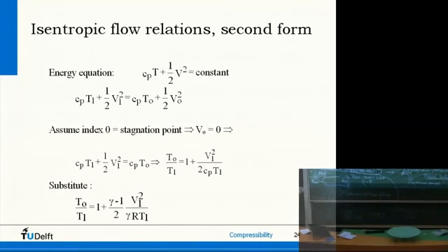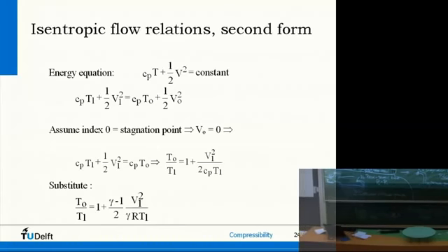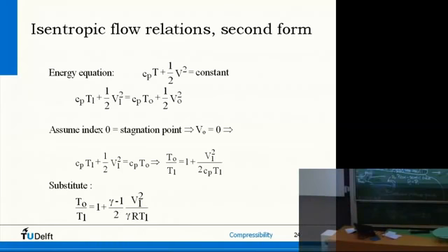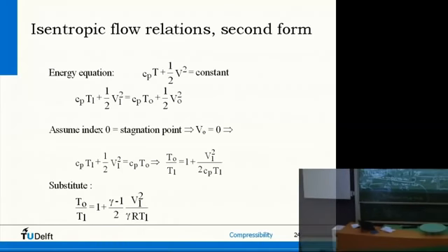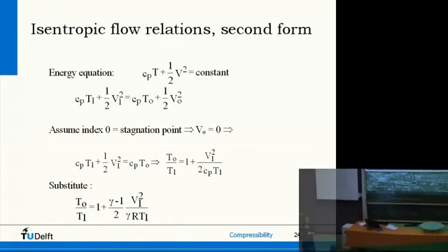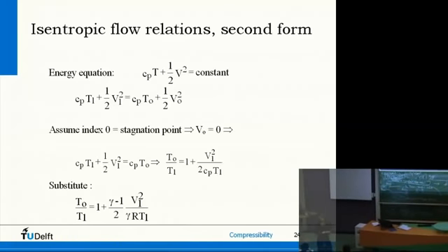Yes, question, sorry. Why do we actually use equivalent airspeed? I mean, yeah, because it's in the Anderson book and it is a good concept. I don't think you use it that much. The question was, why do you use equivalent airspeed? Well, it's hard to measure densities, but you can derive densities from temperature. So if you have an actual temperature measurement, it's not a problem like this. But sometimes people don't have it, and then they use it as an approximation. But especially close to stall, I wouldn't recommend it.